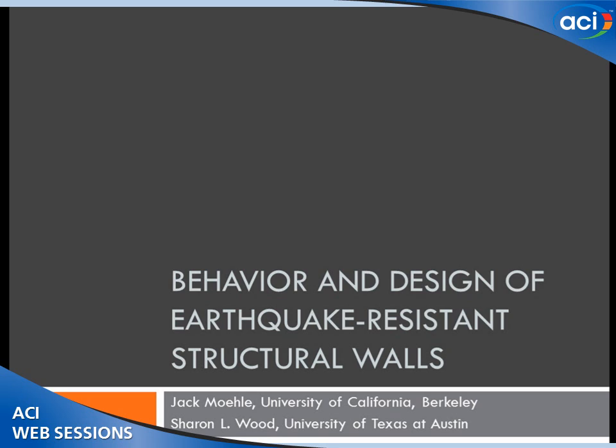The explanation I usually hear is that the software is not an analysis tool that's intended to analyze and exactly represent what's going on in the building. It's a design tool. And as a design tool, if one can reasonably reflect the main parts of the inelastic response, the yielding of the longitudinal steel, and use those software to estimate what the shear and other demands are, that's enough. It doesn't have to be exactly right.